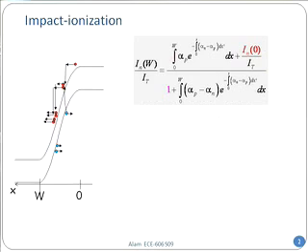looks something horrendous like this. But it's not too bad, because as electrical engineers, we'll actually begin to throw away most of the terms and only keep the ones that are most interesting. But you can sort of see why the solution has to be like this, right? You can see there are lots of exponentials floating around. And when you have exponentials floating around, that's sort of saying that if you put a small amount of current on the one side, that is going to multiply geometrically, 1, 2, 4, 8, and by the time it goes out to W, a huge amount of current will go out. So therefore, there are lots of exponentials floating around.